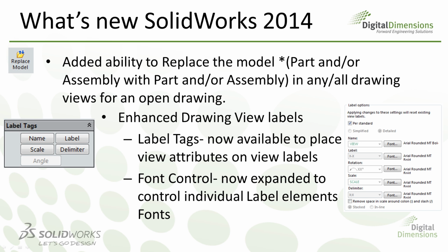Also, what's new in SOLIDWORKS 2014 for drawings, they've added the ability to replace the model in any or all the drawing views for an open drawing. Now let me clarify here, this can be either a part or an assembly, and you can swap it out with either a part or an assembly file type.